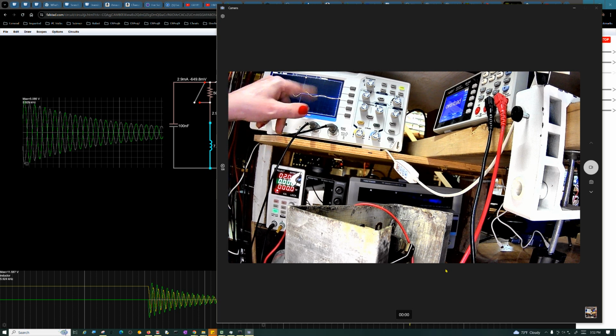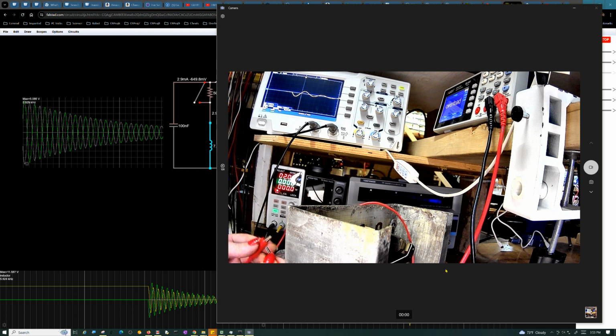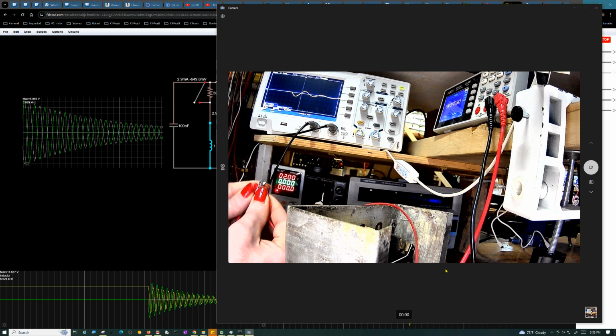And again, remember, this is heavily damped, so it's actually going to be higher than that in practice. This capacitor I've got on here is only a 100 volt capacitor, so I don't want to go any higher than this. But it proves that yes, you can use a parallel tank circuit to generate high voltages. Unlike everybody out there thinks, you can do it. So this is proof. I mean, here I'll run the test again.